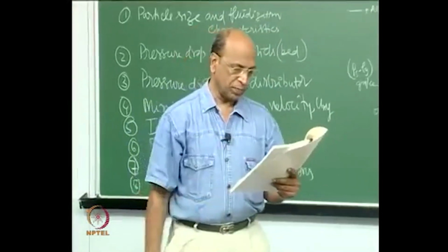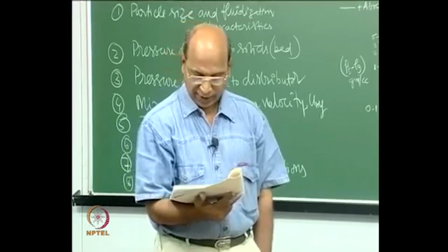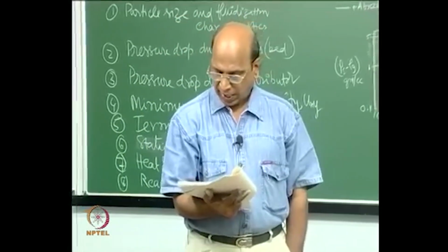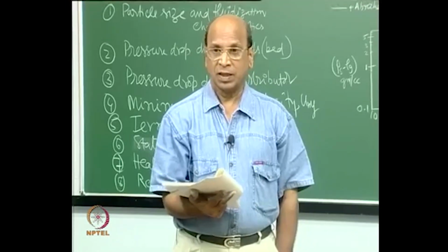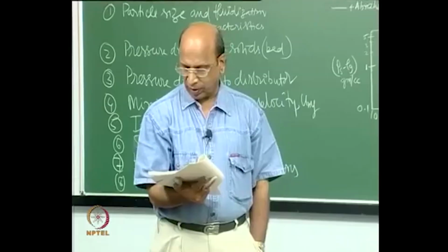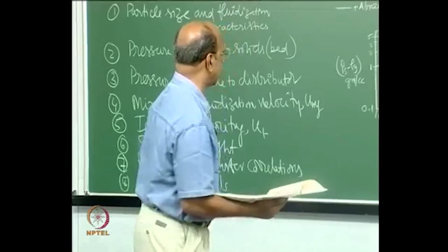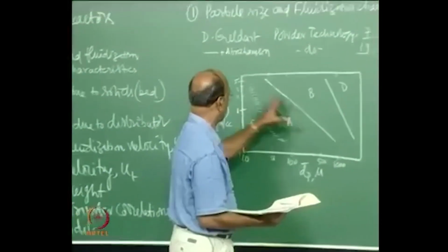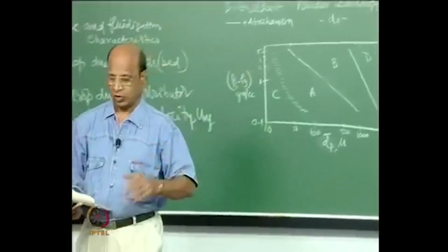Full stop there. These solids fluidize easily with smooth fluidization at low gas velocities and controlled bubbling with small bubbles at higher gas velocities. Full stop. FCC catalyst is representative of these solids. Those are the typical powders. Actually, there is a lot of range here, but still we are somewhere around here. Those are good representations of group A.